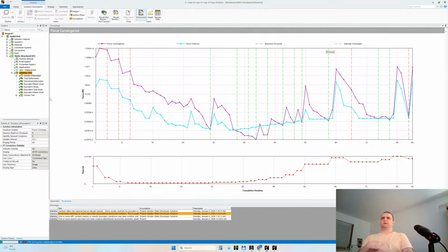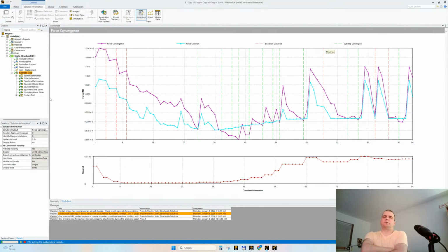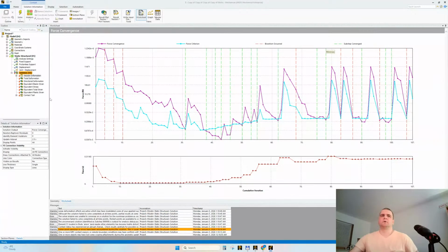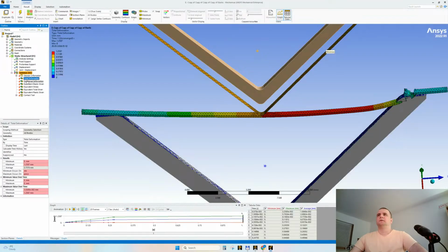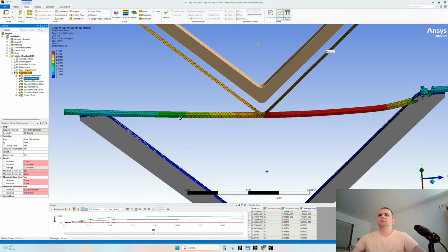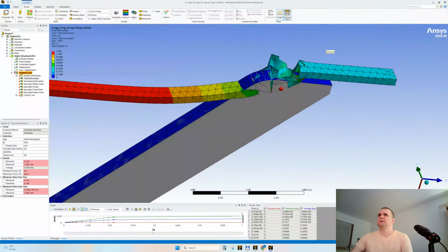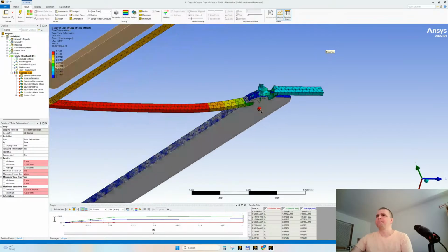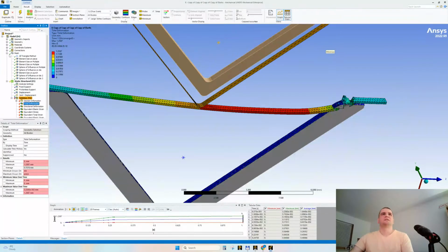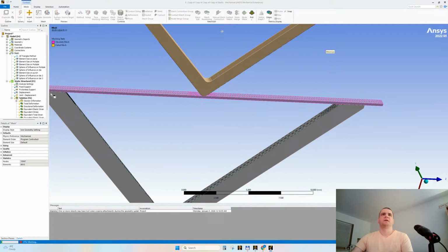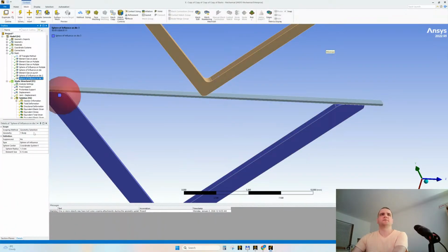So remember, the parts that are not important, you can make them rigid. We only investigate the workpiece here. Does it work? Of course not, because we have this problem with the rigidity here. Let's go back to 0.15, generate mesh, and maybe we'll refine these two.